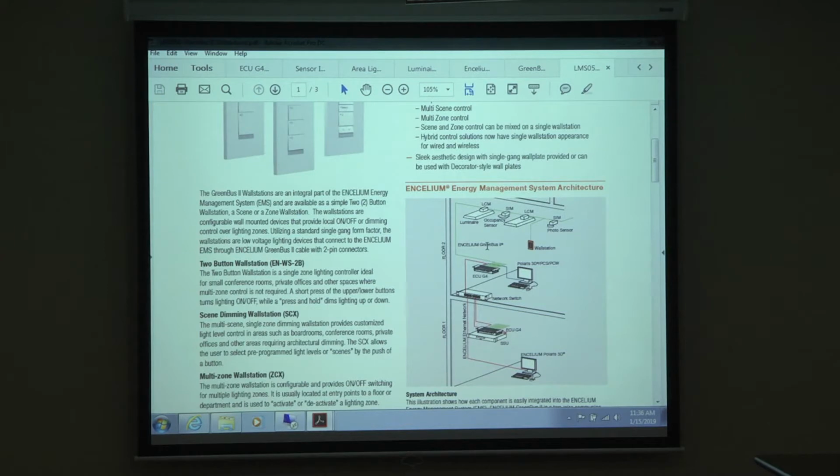The server that stores the backup, you use that to log in and out to control and manage the software, right? You integrate with BACnet AV through the server. You log in for your everyday management through the server, SSU. The ECU stores all the information and receives the instructions that you put in, which means that you press a button, and a signal is sent through the green bus cable from one device to the next. It goes real fast though, right? You press a button, it goes to every device. Run that cable, device to device, back to the ECU.